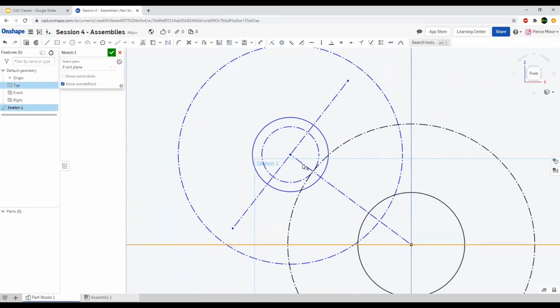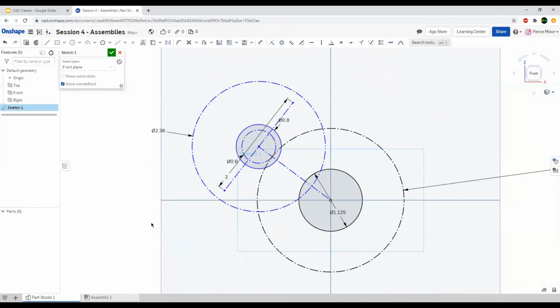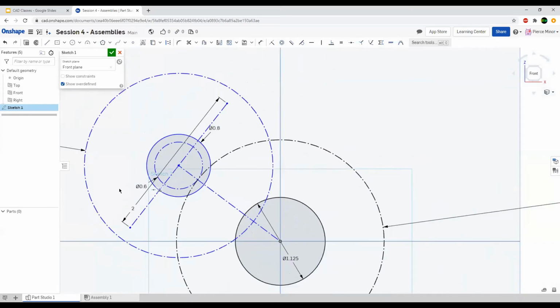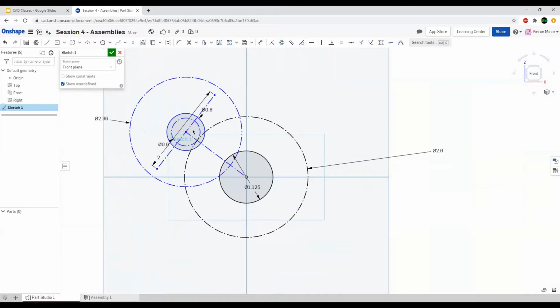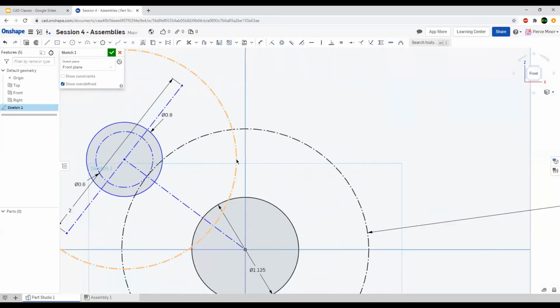So what angle do I want to have these at? Well, I'm trying to keep it relatively compact. So I think a pretty good dimension to have would be, so if this is the diameter of the motor and I'm planning to mirror this whole thing across to over here, I probably want some separation between the two motors, right? In this case, I'll go with a total of an 1/8 inch of separation.